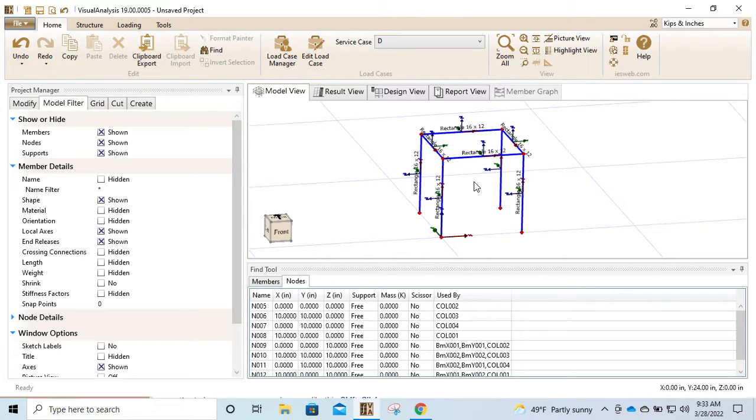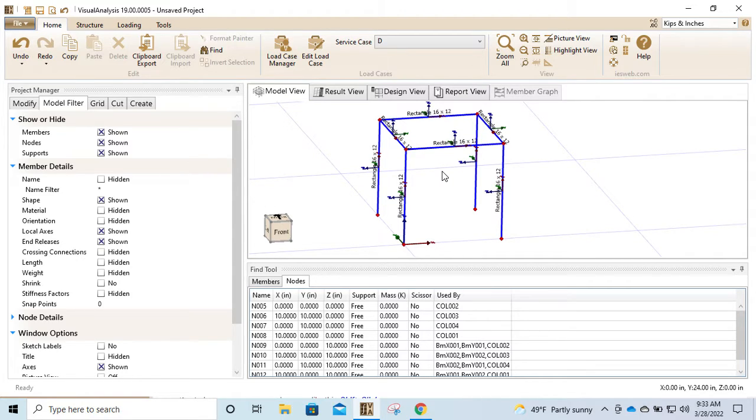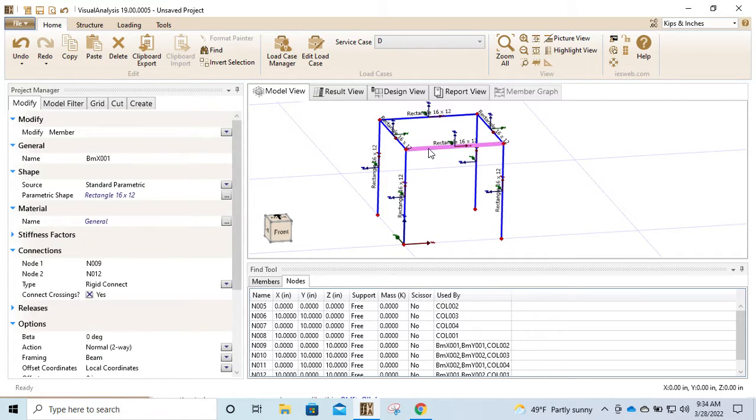All right. What's critical with, say, a frame of this nature is our releases, right? We talked about in class the idea that we have shear tabs, which might not transfer rotational stiffness, but we have translational stiffness. Okay, moment frames, it would translate full stiffness, right? Which is what our elements are derived based upon, is transferring of that stiffness between one element and the other. Well, in order to get rid of some of that,